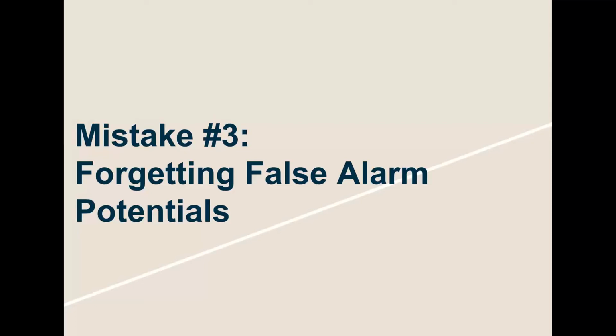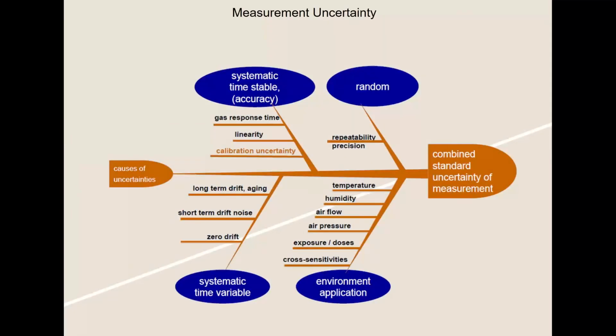A lot of times also folks think that they are having a false alarm when they really are having an alarm. They just can't find the actual leak. So you do have to take it really, really seriously if you get any sort of readings on the sensor. The other thing to understand is, what are the environmental conditions, right? What is the humidity range that could be present?